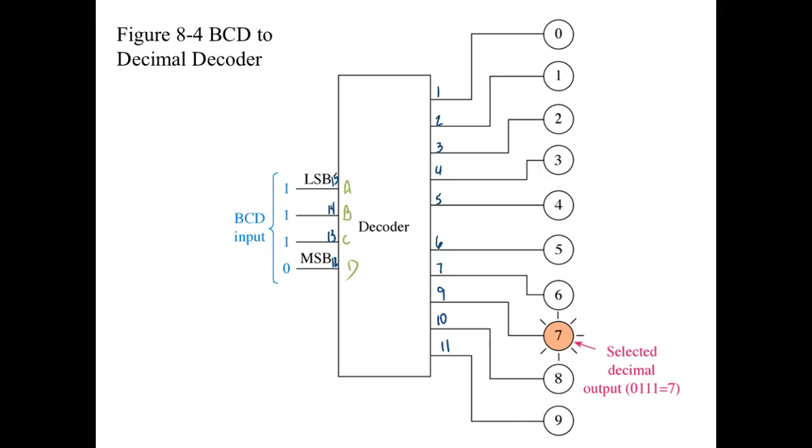So when we look at the schematics in the back of the textbook, you'll see no power pins in the whole thing, because the more stuff you add, the more complicated the schematic gets. So leaving off the power pins, that's at least 2 pins that we don't draw, but it's understood that they're connected, yeah.